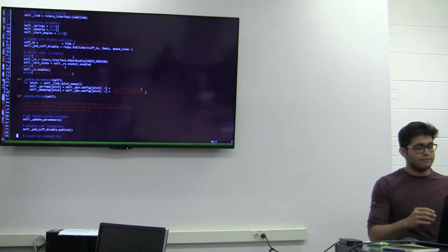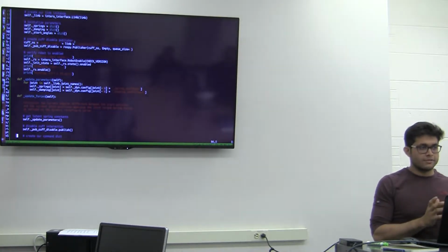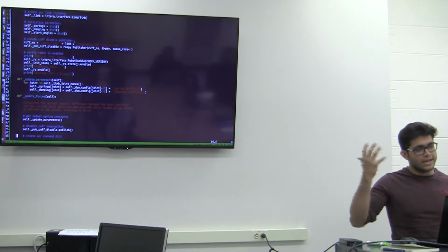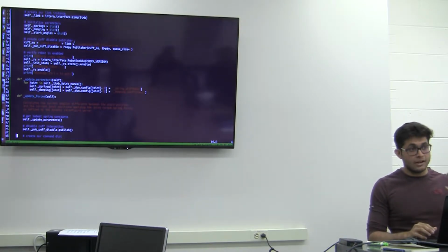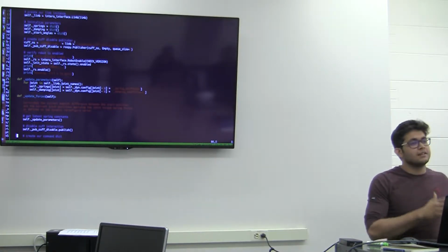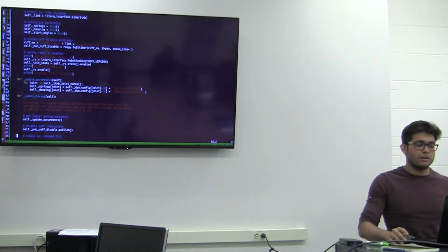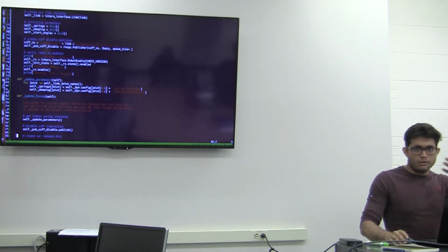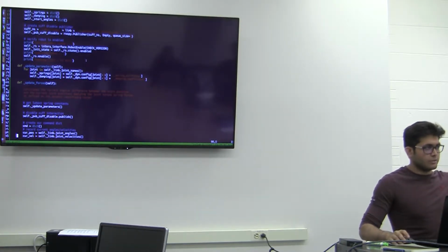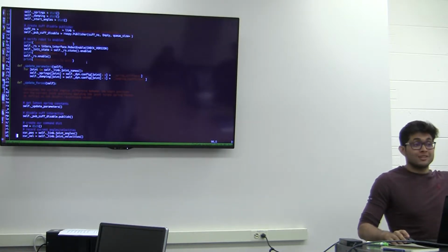You'll realize further down that the start angles are just called from the URDF or from the home position that we already stored, or the Sawyer has it in its background. Never ever change the start angles. You can change damping, you can change the spring coefficient, but please never change the start angle, because in that sense you are shifting the home position somehow. You can technically change it and the home position still be the same, but I would recommend not to change it unless one of us is there, because you need to make sure your start angles are good.